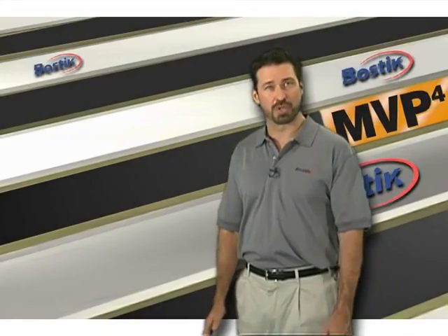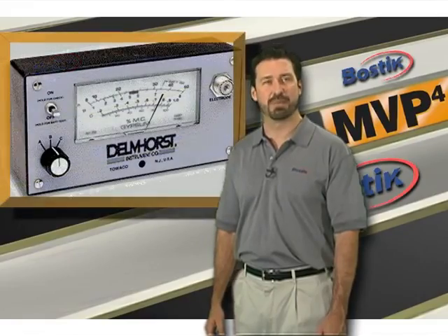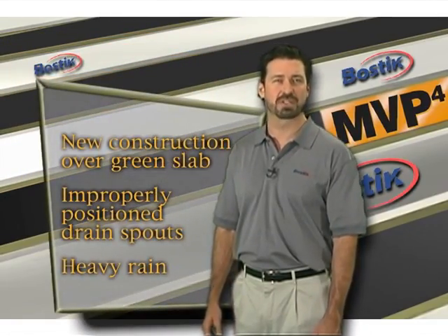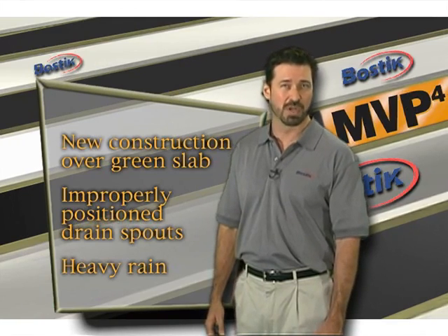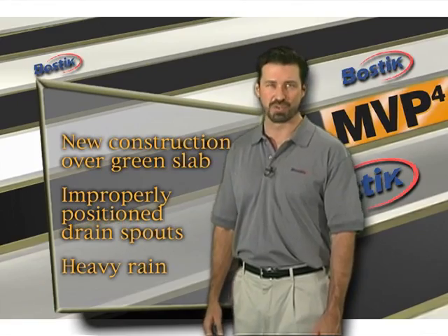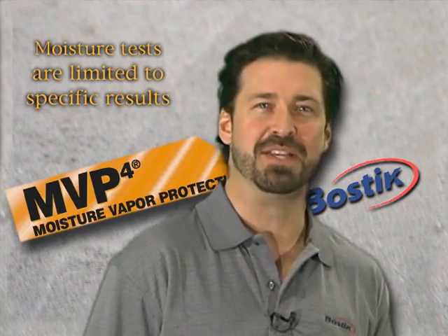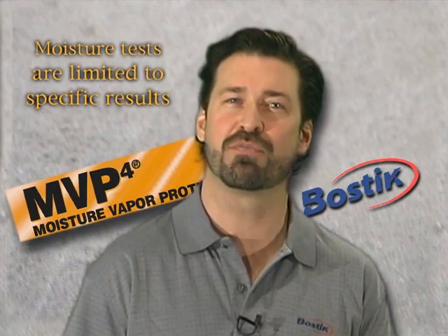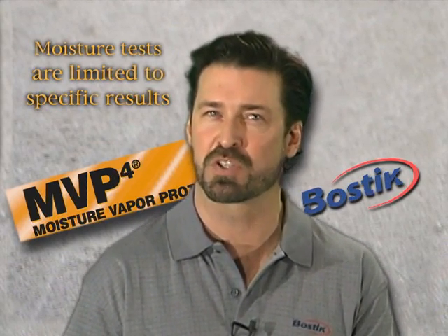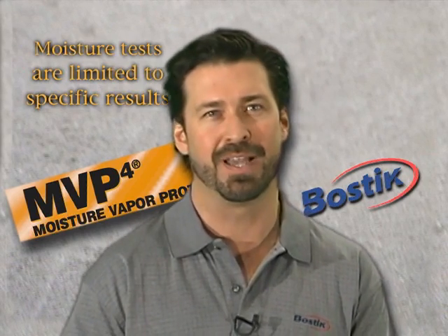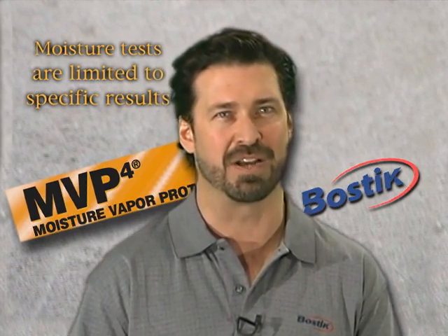Another situation could arise where a subfloor moisture test may produce high readings, which were a result of new construction over a green slab that didn't have enough time to cure, improperly positioned drain spouts, or a heavy rain from a recent storm. The bottom line is moisture tests are limited, since they can only give you results for a specific point in time in a specific spot, but can't predict what the actual results will be in the future and ultimately can't guarantee a dry slab.